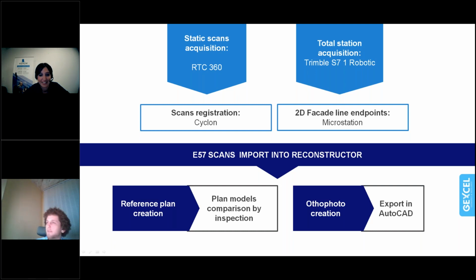Exactly. So on site, now we use our Leica RTC360, again pointing out that even though we also use Faro instruments on site, it does not really matter. You just have to put it and register it in its place, and then go to Reconstructor. Also, to provide the proper geodetic network, we have our Trimble instruments. And we have all the plan data, also 2D, within MicroStation in the proper place at the proper position.